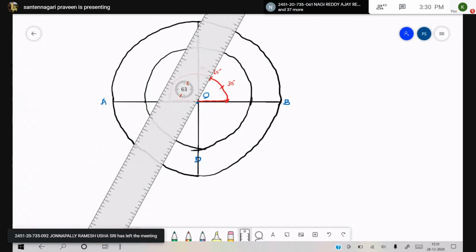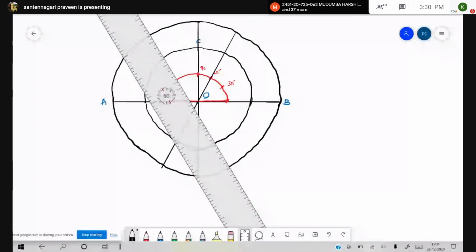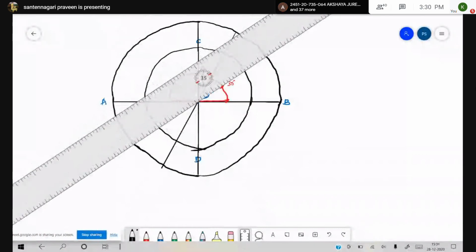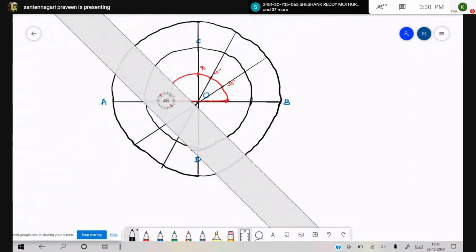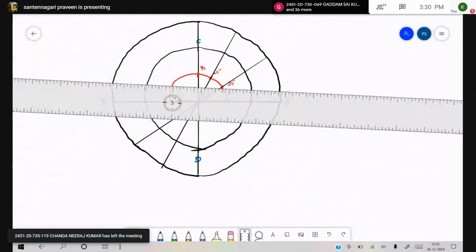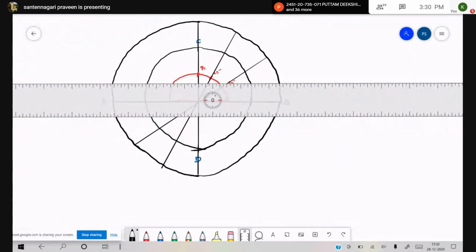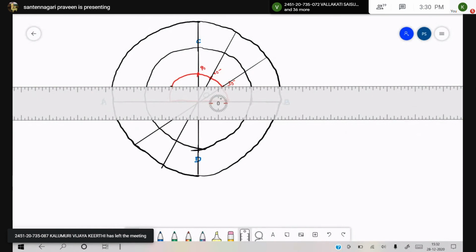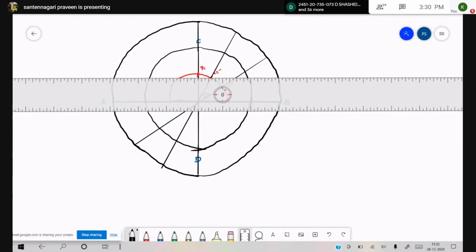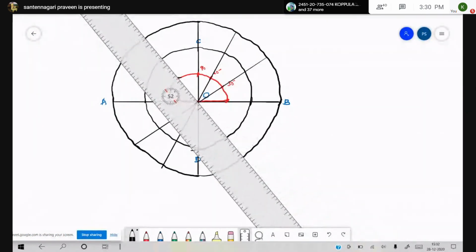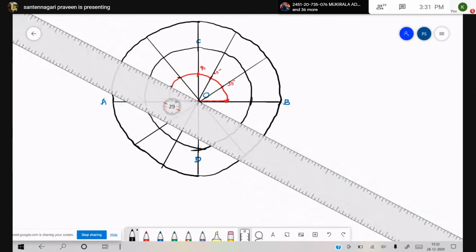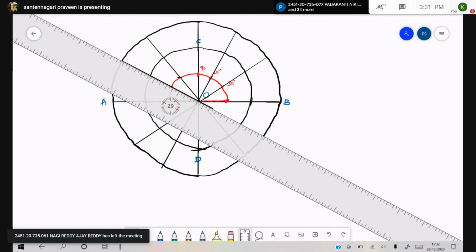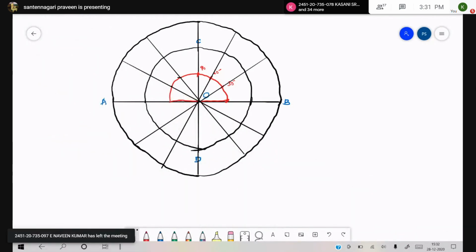Like this. Since there have to be two, below your XY center line and above your XY center line, both the lines cut. Draw the bisectors cutting these lines. Similarly on the other sides also I am doing it. Here also you mark your 30 and 60 degrees angle. And simply we have divided this into 12 equal parts.